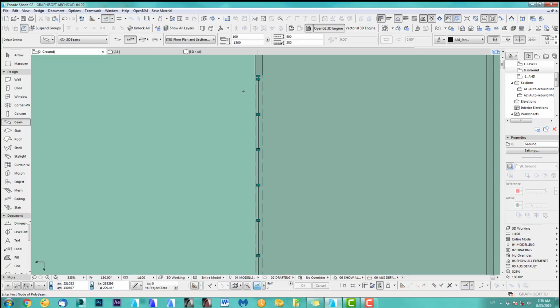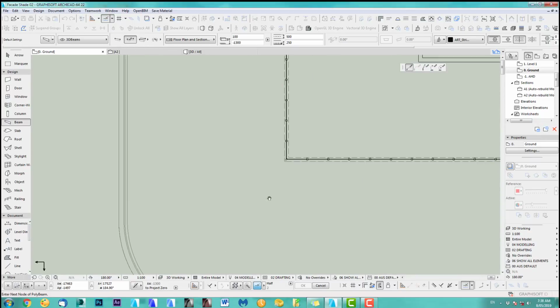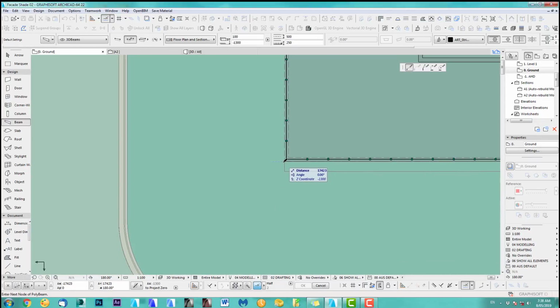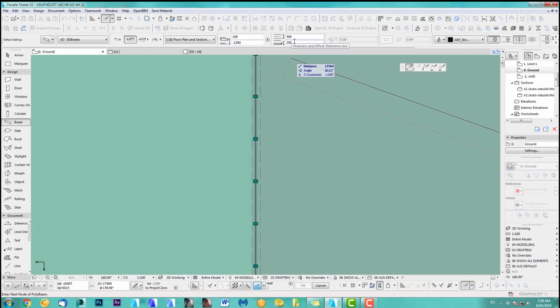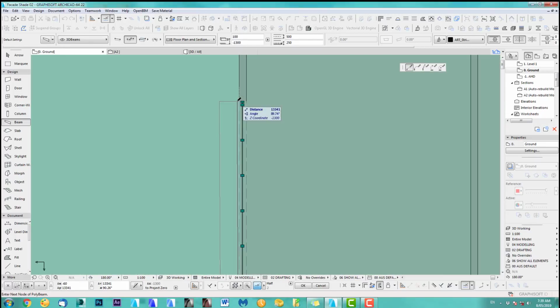And as you can see, it's going the other way around. So let's start this way. And by the way, you see the beam is on one side. What I did is the 250, actually I'll show you, this is quite nice. I divided 500 by 2, so it's 250 now. If I leave this on 0, what usually happens is the beam is drawn in the middle. But I like to draw the beam just from one side. So divide 500 by 2, 250, so the construction line moves to one side. All right, great. Let's go this way and this way.